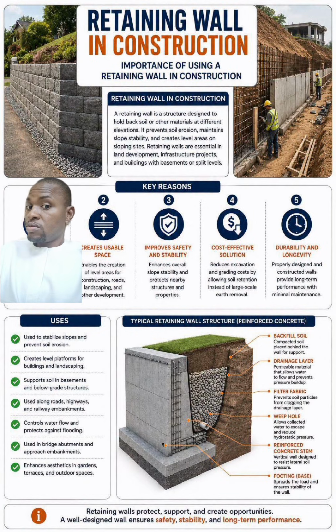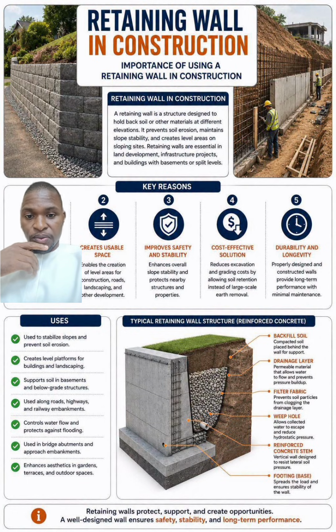Like for areas where you have large erosion coming up, you can actually construct your retaining wall structure. Then you backfill, you compact and backfill to bring it to the road level. Thereby it helps you to control water flow and protect against flooding.